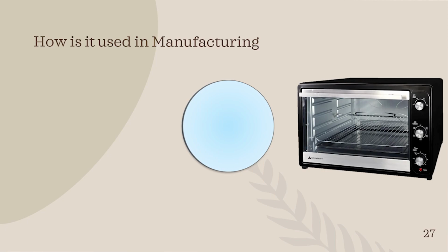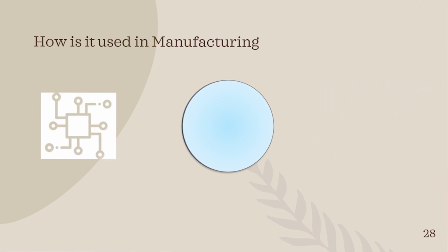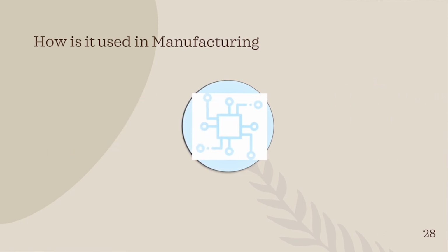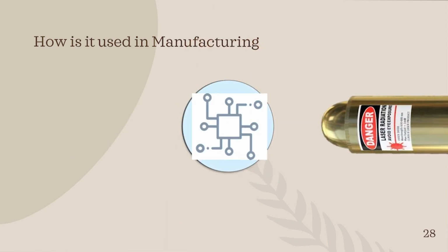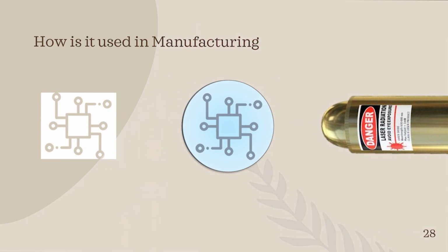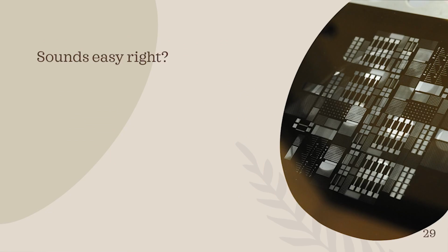And then as it grows the oxide layer, now let's say this circuit is the pattern we want to put on our semiconductor. We take the inverse because we need the mask, remember, because anything that gets hit with the light, we put it on. It hits with the light. Now all of this has been made so that we can then dissolve it. Sounds easy, right? It actually is, at this scale, at least.